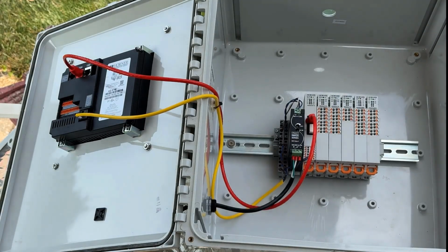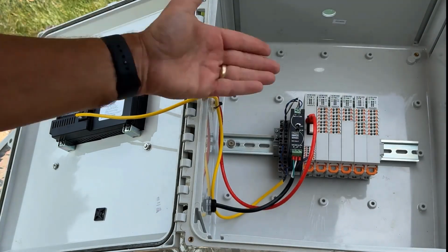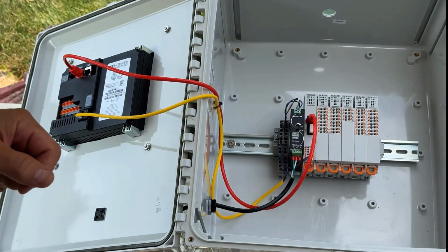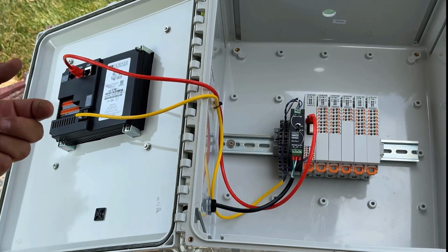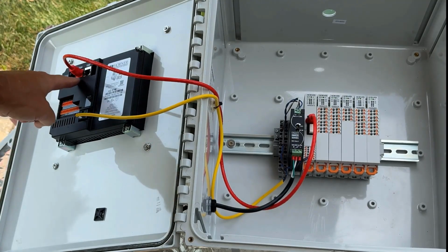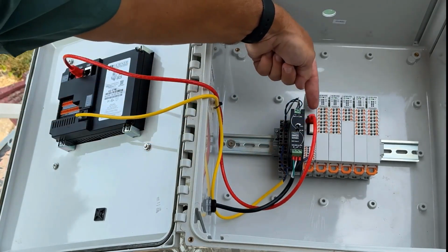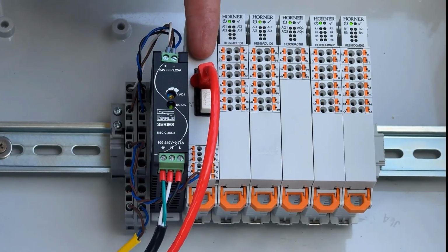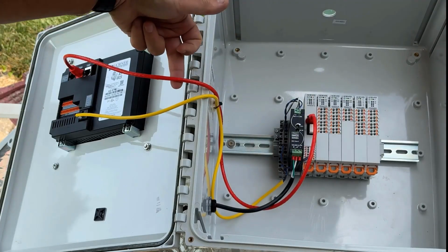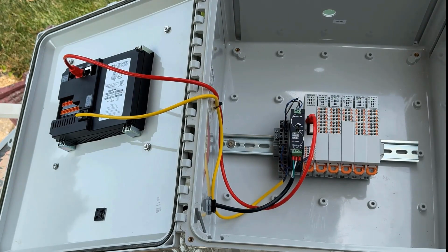So this is our simplest scenario, where we have 2 components. The CAN wiring never leaves the enclosure, and both components support RJ45 for CAN. So we have got our X7 with its CAN port connected to our CNX OCS IO base connected to its RJ45 port. In this case, it turns out that a 3-foot or 1 meter RJ45 patch cable works well.